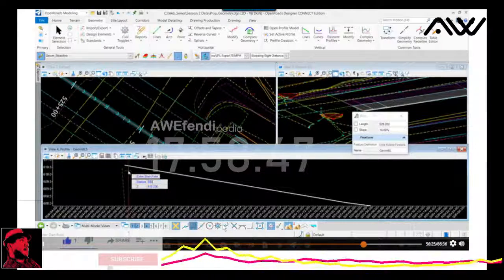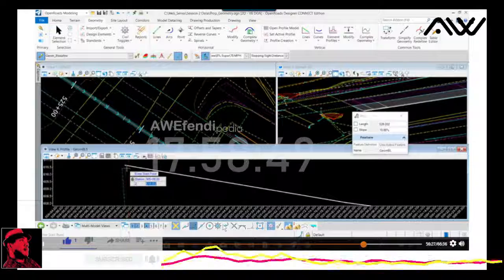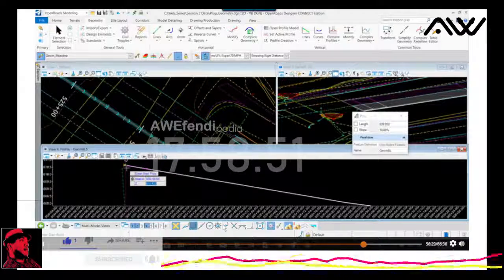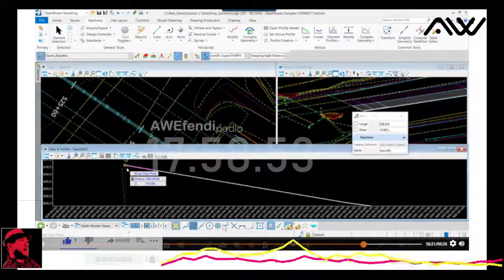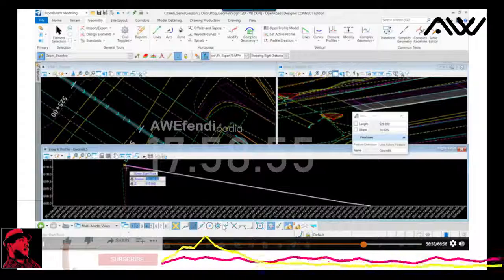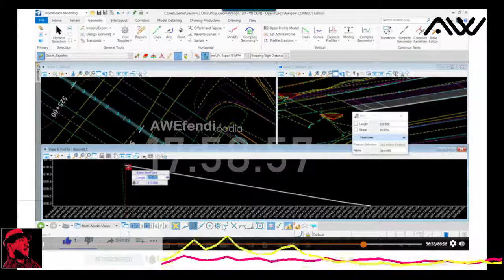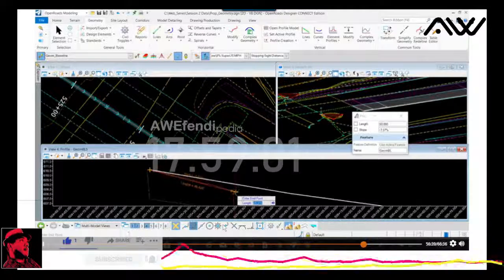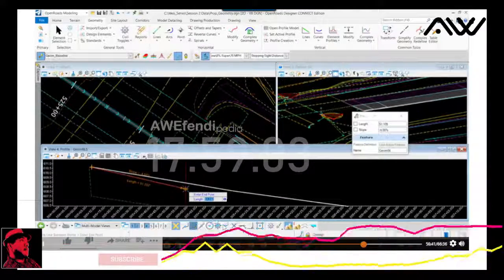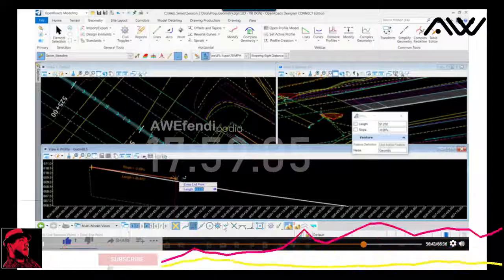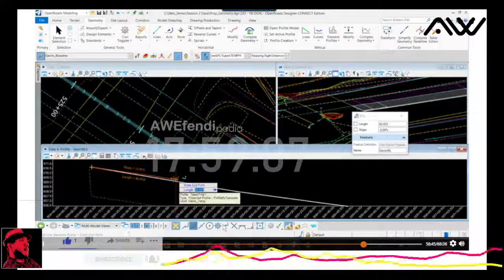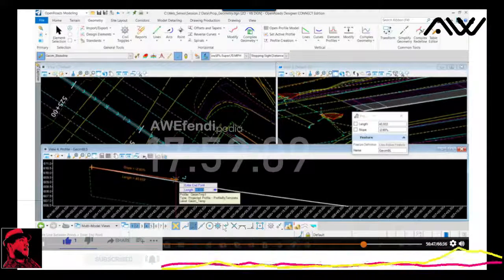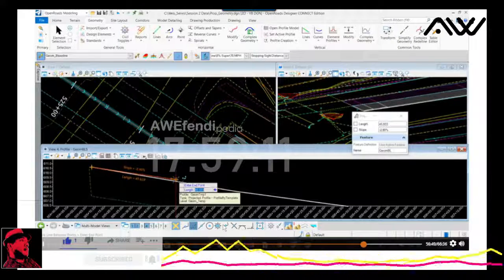And I'll, again, tab key to lock, and then I can lock in a specific elevation if I want. Tab key to lock it. Data point now to begin drawing that element. So Civil AccuDraw can be used in profiles as well, okay? Now, as we're laying out this element, I'm going to place tangents, and then fit arcs between them in this workflow.